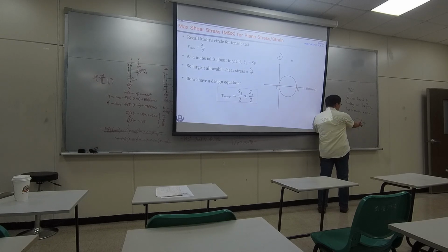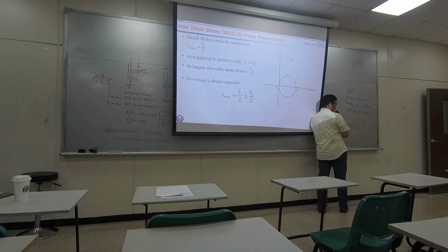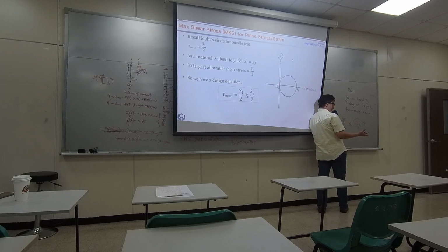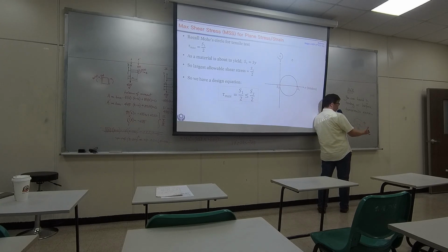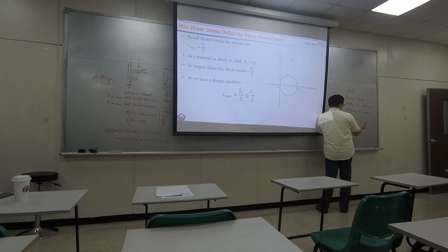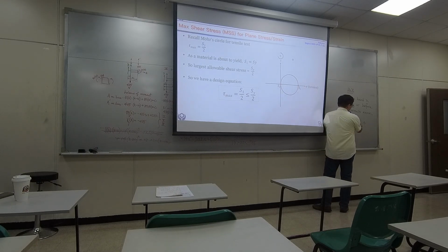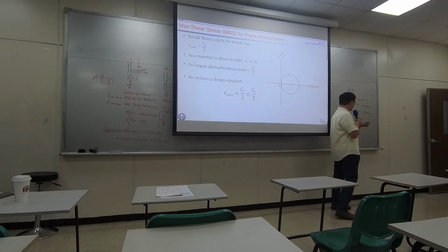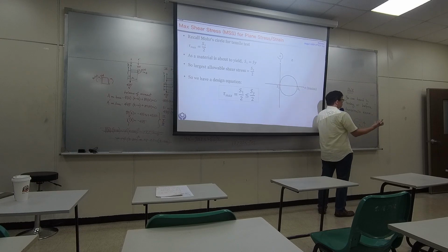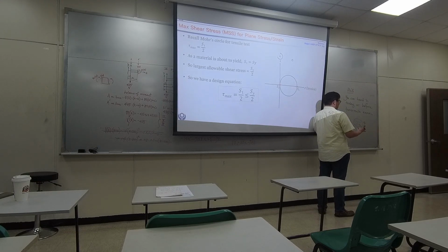So the yield strength of copper is lower than the yield strength of steel. So if you have a mechanical design and originally you were using copper, it's too soft, you change it to steel, it's stronger. That action means you are upgrading the upper limit for that equation. So that's one way to make your design safer.